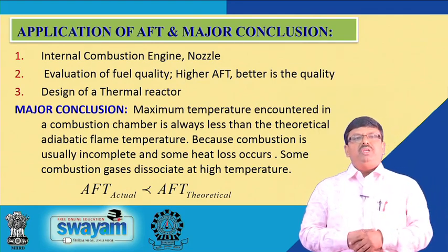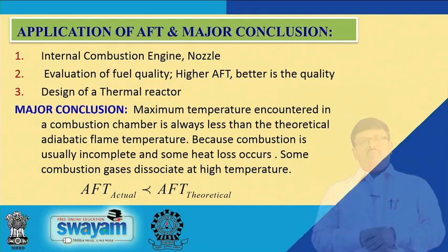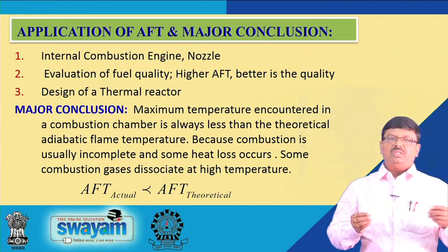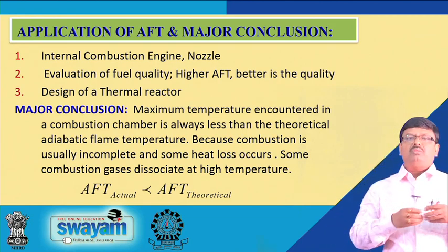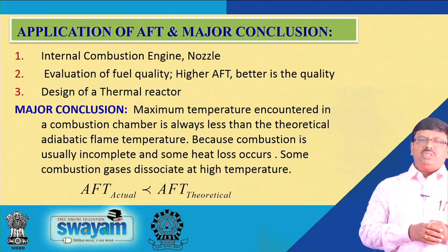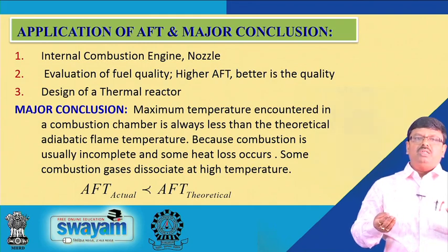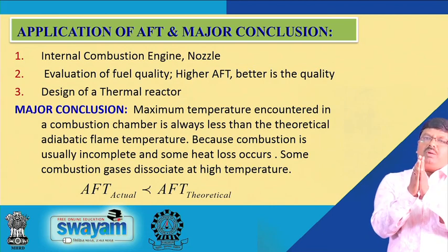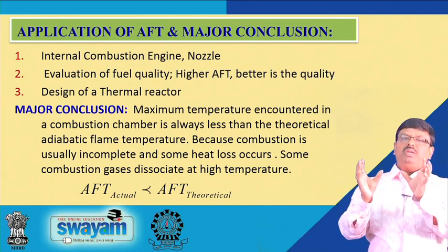Now, these major conclusions. This is one of the very important conclusions: the maximum temperature encountered in a combustion chamber is always less than the theoretical adiabatic flame temperature, because combustion is usually incomplete and some heat loss occurs, and some combustion gases dissociate at high temperature. This is very obvious and understandable to all of us, because if there is heat loss from the system to the surroundings, definitely the temperature will be less. So, the actual flame temperature and the theoretical flame temperature will be different.